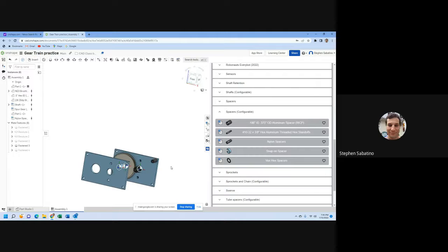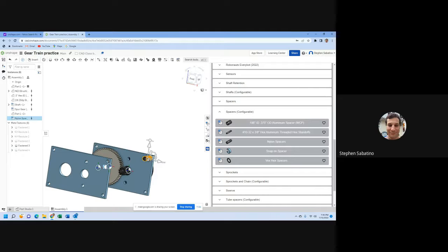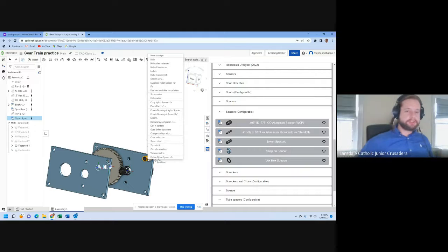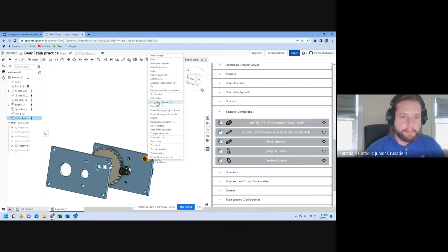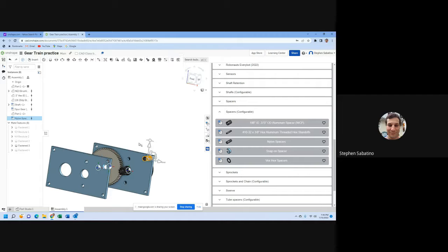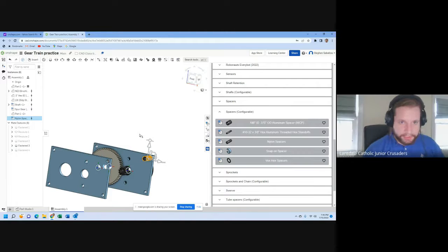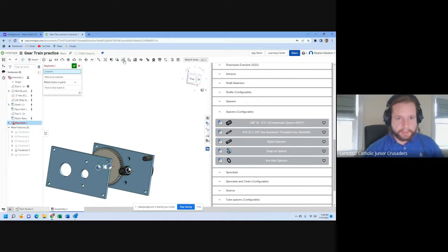Now, I have to make 4 of those and keep making them? No, those should be the same part. So you could probably use a replicate command if you'd like, which is up at the top. It looks like a Lego, kind of, to the left. That's a pattern. That's replicate. There you go.